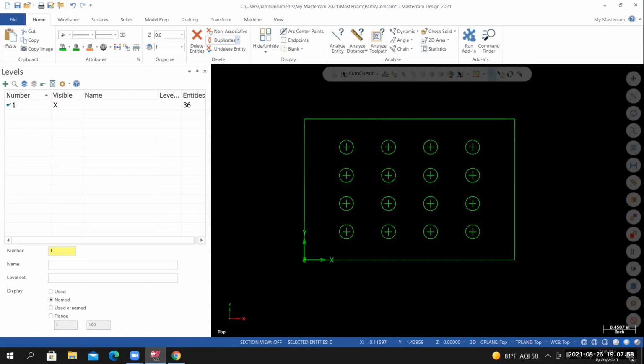So will it affect the toolpath if you have a duplicate point? It can, yes, it can. It'll try and drill 2 holes there. So if you got both of those added to the geometry of that toolpath, it'll drill it once and it'll drill it twice. Not a problem, it just kind of wastes time. Got it. Okay, all right, thank you. You're welcome.